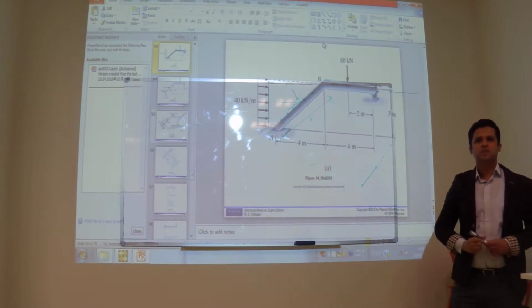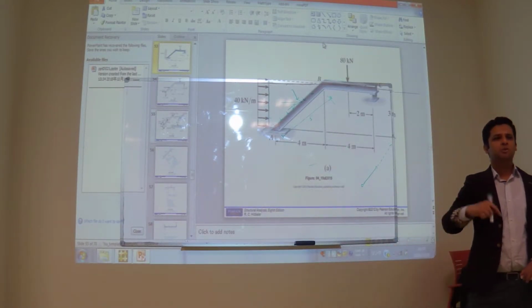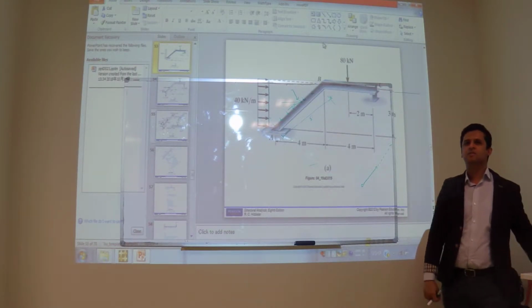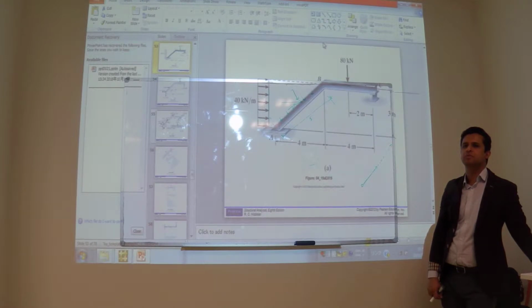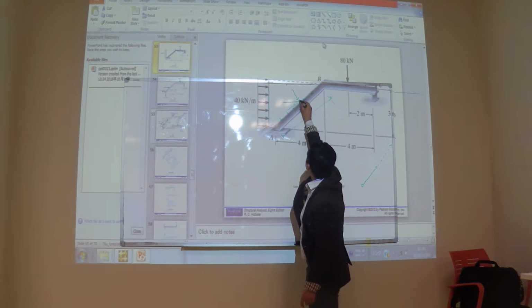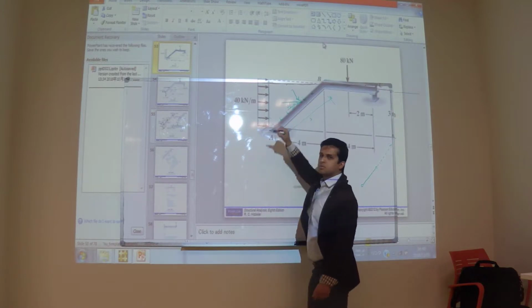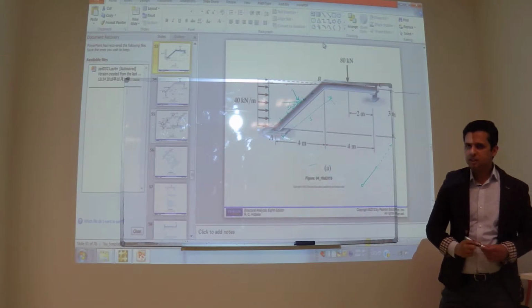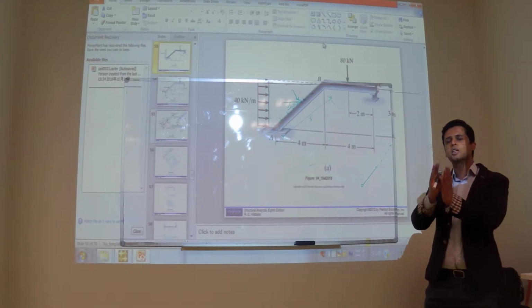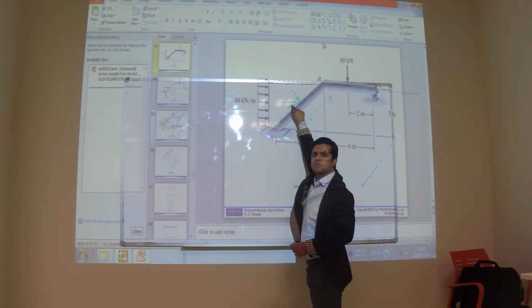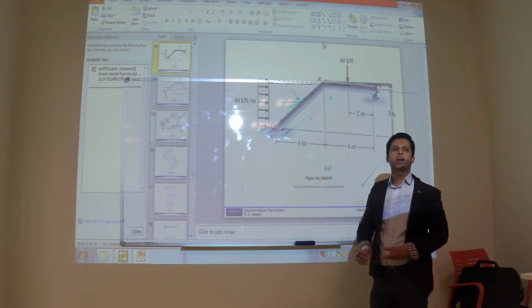How many of you do not understand what I am doing here? Raise your hand. Teacher, do we directly divide by 5 or by the cosine theta, which would be 3 over 5? You already converted this load, based upon this angle, into two components. So again there is no need to take any cosine or sine, because you have already converted this component using this angle.